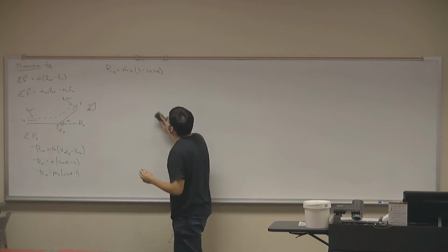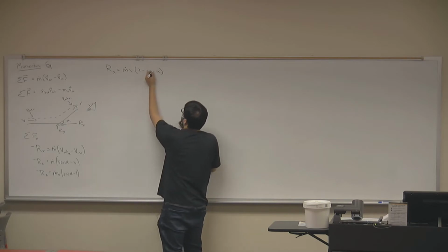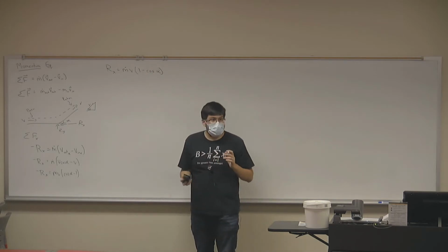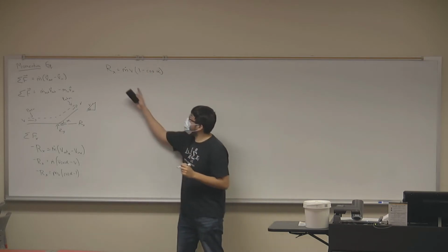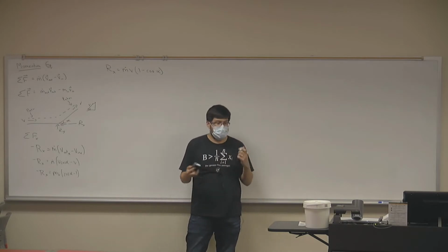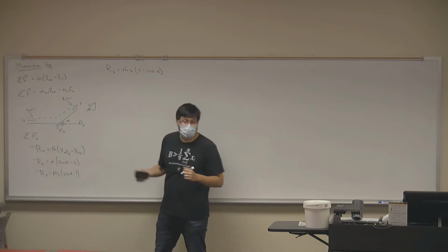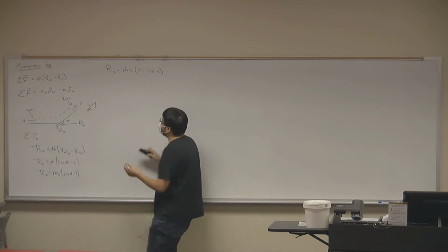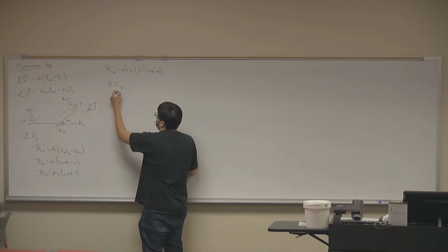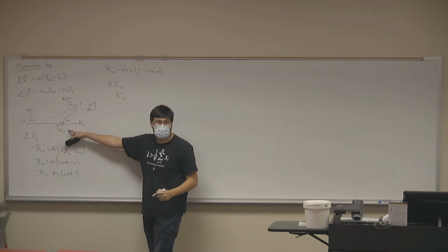And what does this tell us? Well, the greater your angle, alpha, then the greater the reaction force needed. In other words, the greater the force from the fluid. So the greater the deflection angle, then the bigger the fluid force. We did the same thing in the y direction, where we said that the sum of forces in the y direction were equal to just the reaction force in the y direction.